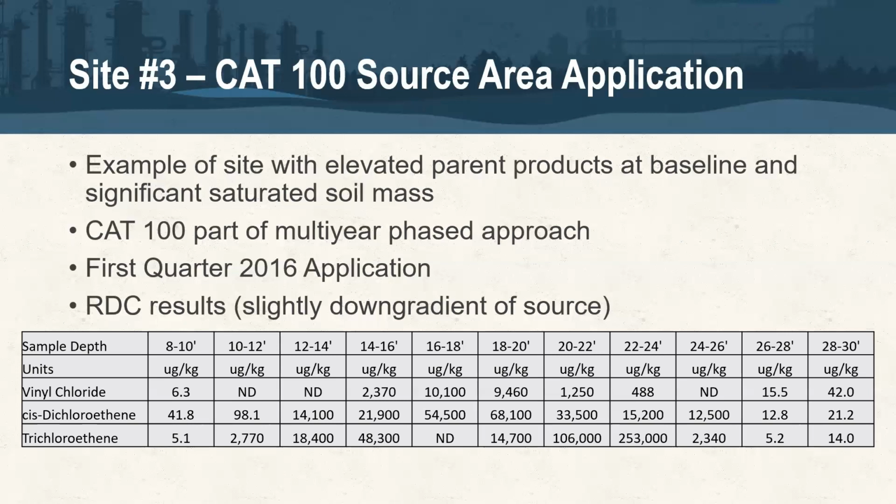And we're driving mass off of soil into groundwater so that it can be subsequently treated. And so when you've got these levels of saturated soil mass, we've got to slowly bleed this out of the saturated soil, and it's going to take some time. So when I show you the data for this particular well, it'll start to make sense, because there's a lot more noise than what we saw on the previous sites.